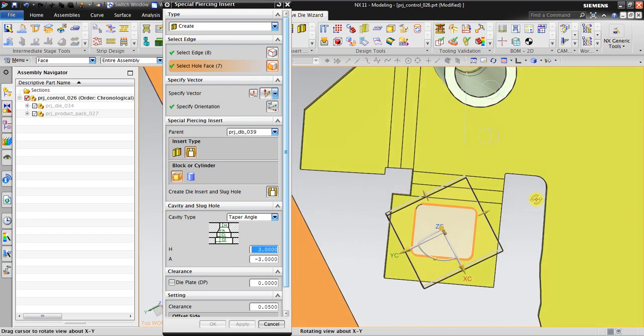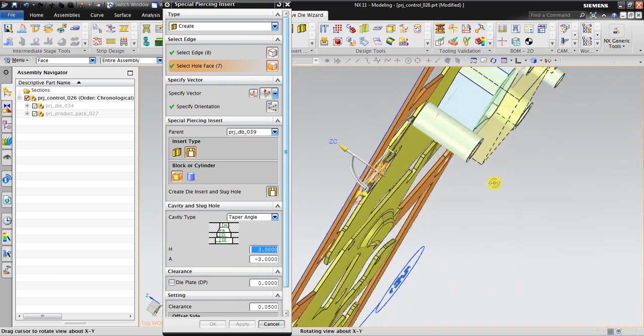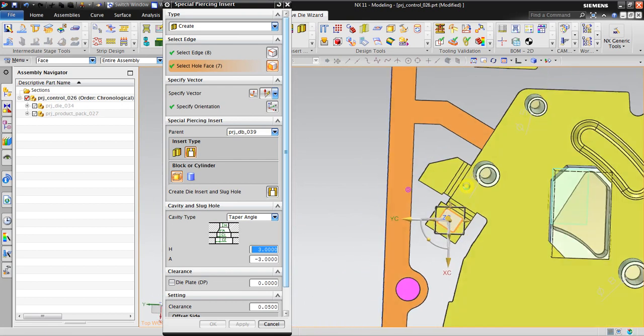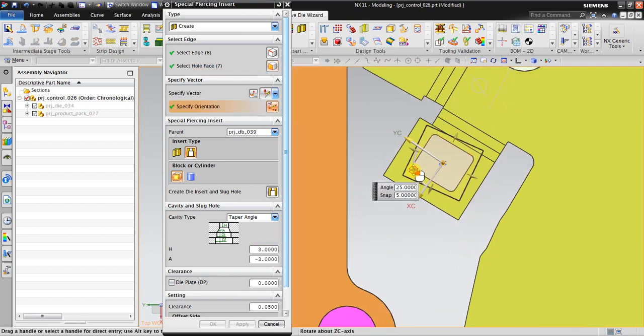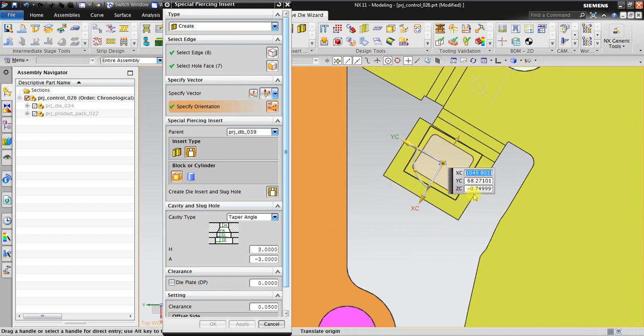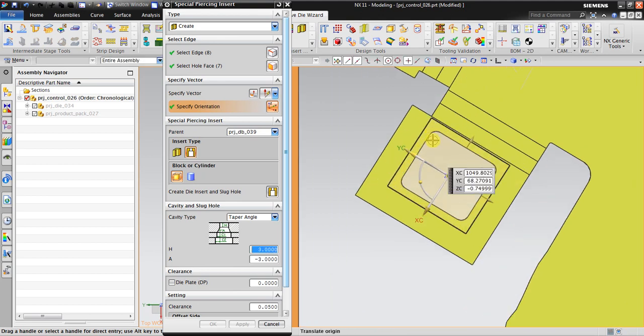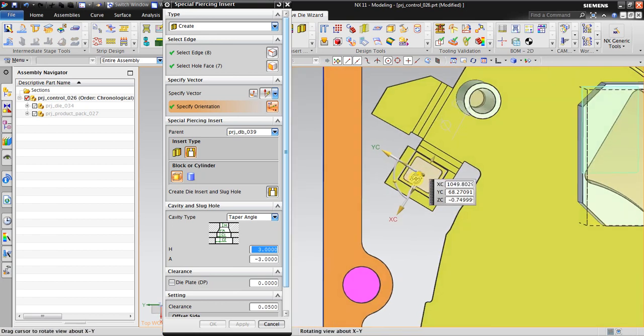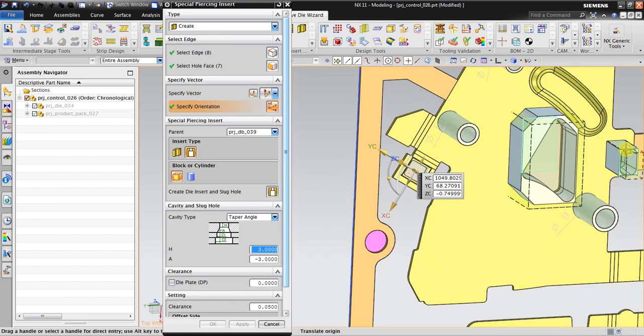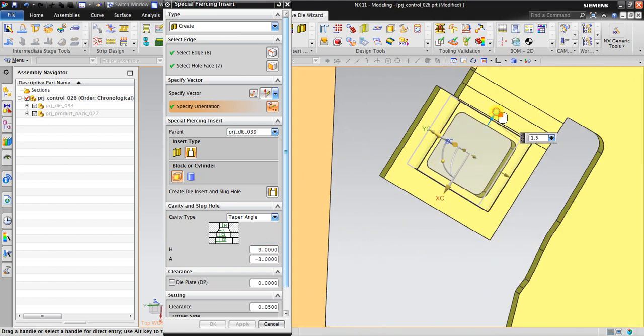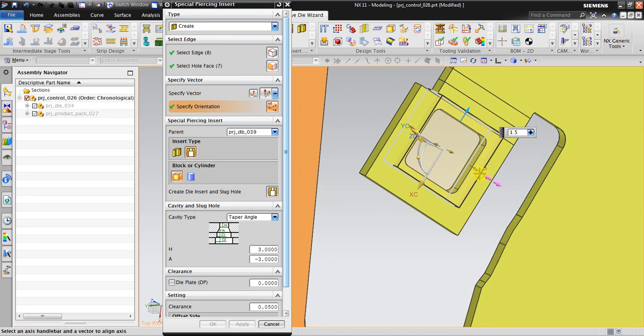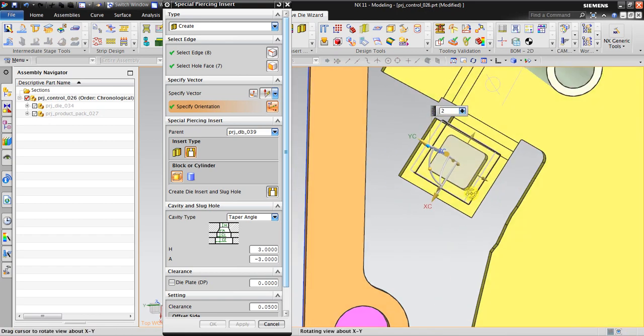Now you see the box is not good for the orientation, so in here I will reorient using this dynamic repositioning. This is good. So if you don't want it too thin like this, you can also increase the bounding box size from the beginning, so you don't need to add the thickness using Synchronous technology for all sides.